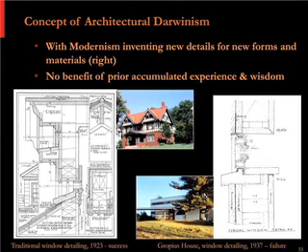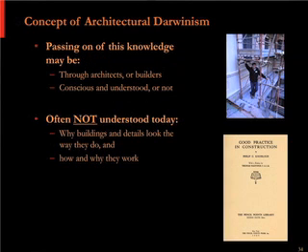So Gropius really wasn't following this whole look, this whole way of putting a building together, of making a window, of creating siding, etc. So he had to invent a lot of his own details to do this, and ran into a lot of problems. So this window detail is highly problematic. It funneled water into the wall under it. All the wood under it rotted out. So we spent a lot of time helping the Society for the Preservation of New England Antiquities, now Historic New England, to restore that, and the windows in the area below them were a big part of the problem.